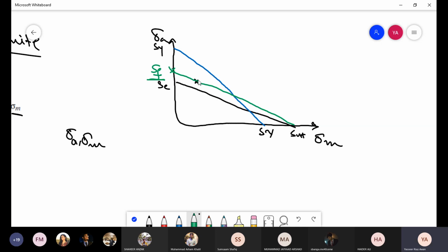Okay, so obviously at this point the load is not completely reversed. So for which stress to aim for, either we can aim for this strength value, or this strength value. The better method is, similar to the Goodman line, to draw another line that moves from SUT and passes through the point combination of sigma A and sigma M, and then extend it to the line where sigma M is 0. And that would give you the fatigue strength, or the reversible stress.